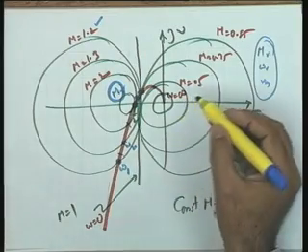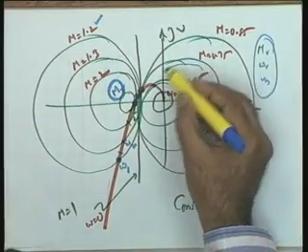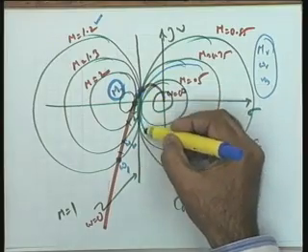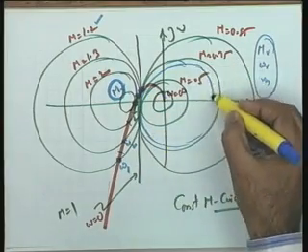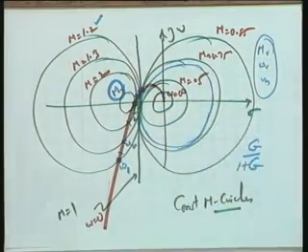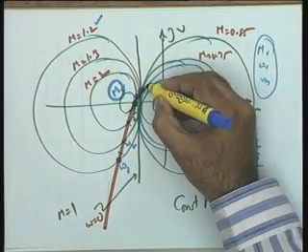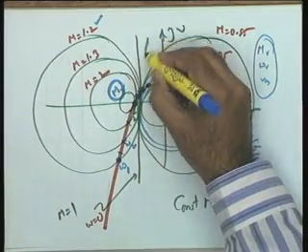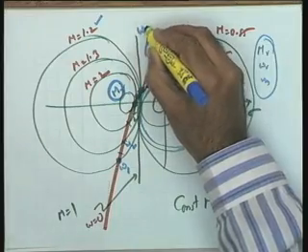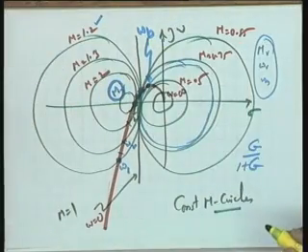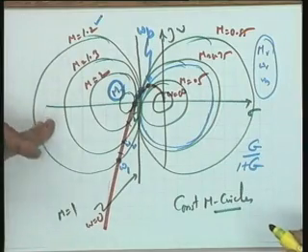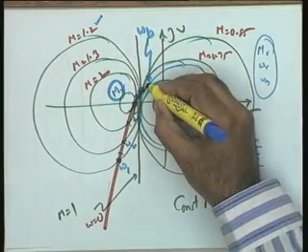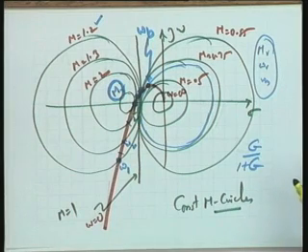In this particular case, let me make it somewhere here, the 0.707, between 0.5 and 0.75, and this is the point of intersection. The frequency at this particular point is nothing but omega b. Again, its evaluation may turn out to be difficult, okay, but yes, at least the route is clear, that if I want to use this method, the intersection is at this particular point, and therefore the frequency at this particular point is going to be our system bandwidth.